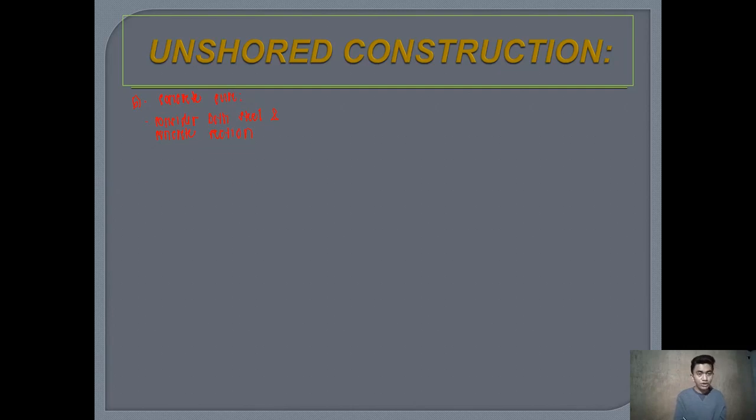If we are going to consider both steel and concrete section, we are again going to utilize the transformed moment of inertia, and what we have computed earlier for the value of y top and y bottom. For concrete cure, instead of utilizing dead load as under concrete wet, we will be utilizing only your live loads. So weight total now will be equal to, what are your live loads given?